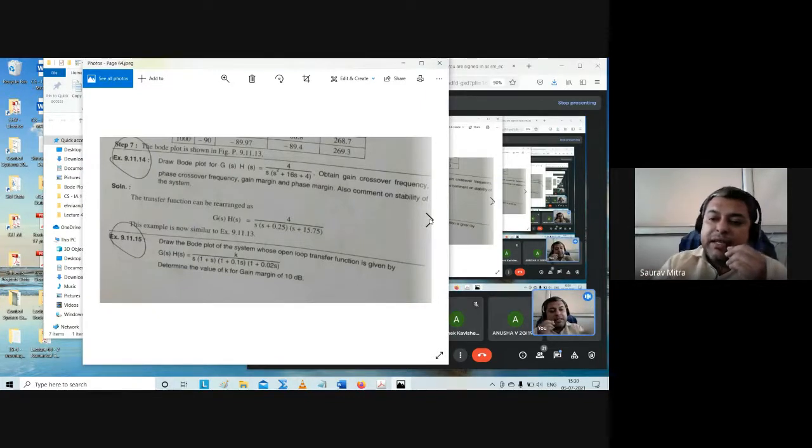So plus 90 minus 270 is minus 180. So with 3 poles, one at 0 and two others, in all such systems you will not find the system phase crossing the minus 180-degree line and going to imaginary. In that case, what was our argument? As s tends to infinity, the system phase was going to minus 180. The system phase never crosses the minus 180 line and never comes below. So omega pc does not exist. If omega pc does not exist, gain margin is plus infinity.